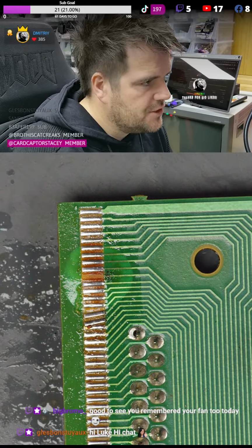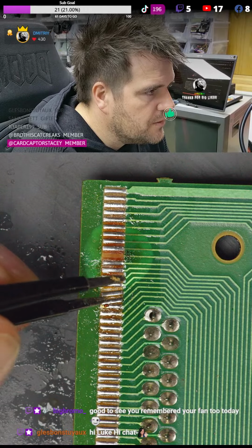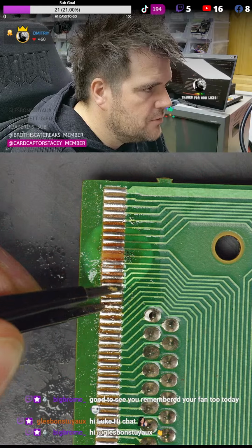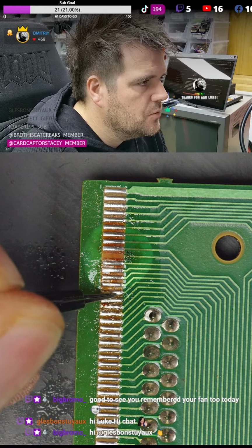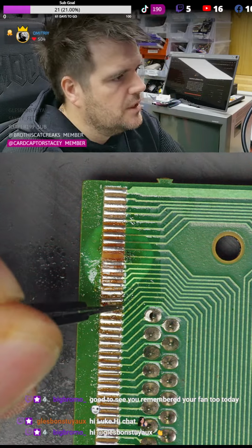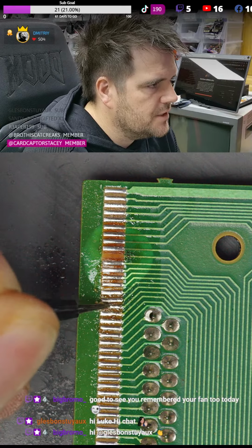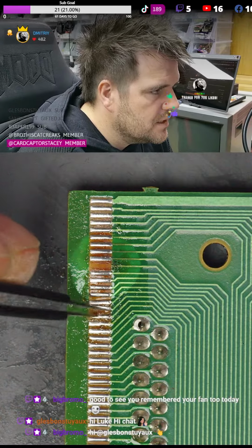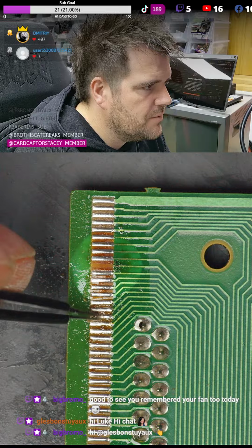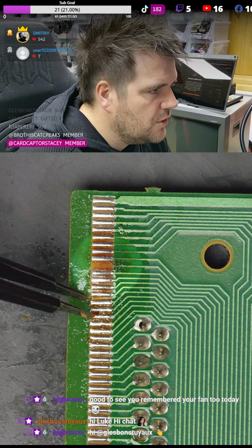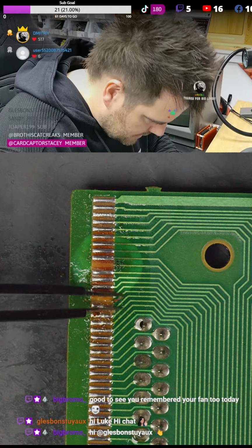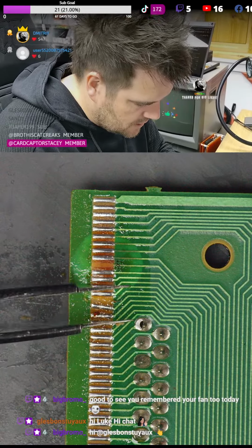So you can see these two pins are moving. You can reposition them while they're in, but we probably want to make a note that once the LCD pin's on, we check these are going to the right place, or maybe even bond wire these two things over to there. We'll see what we do, but let's take note of them. They're very weak. I might just snap them off because they're moving, and then we'll solder wires. Yeah, I'm going to snap those two off because the fact they're already moving, they might be strong, but I don't want to risk that.